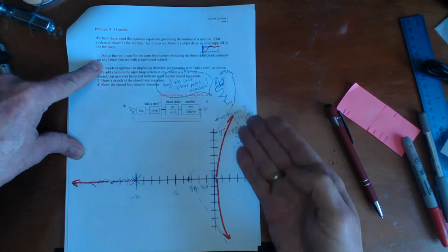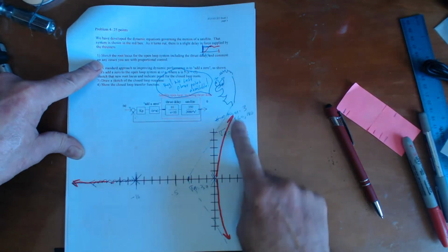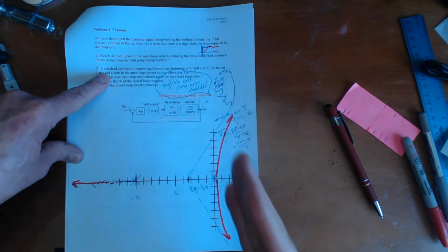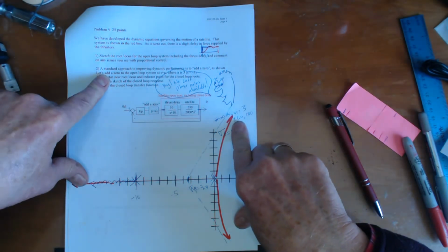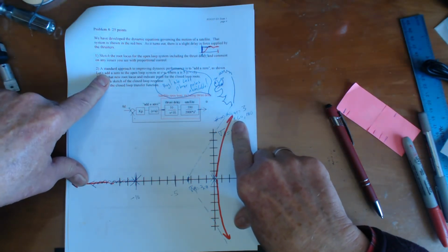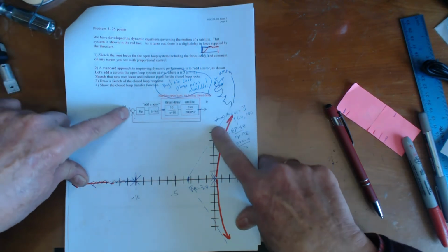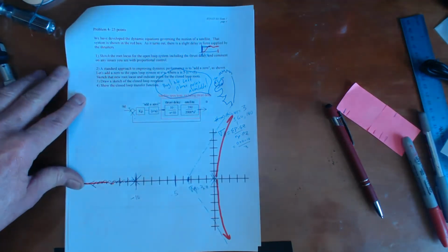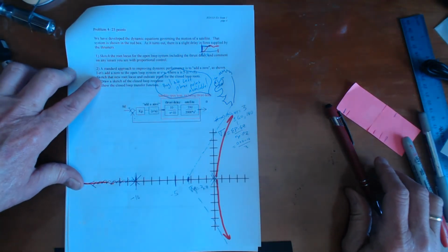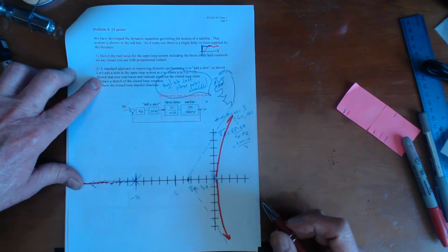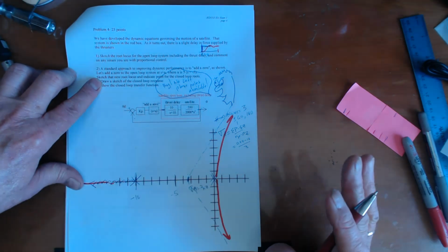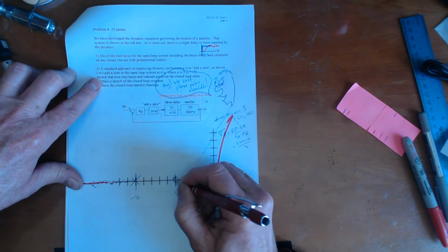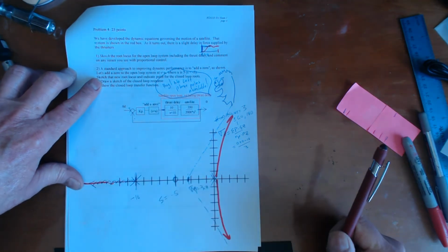If you just use proportional gain alone, you're going to run into problems. So a standard approach, if you don't like the dynamics that your root locus has, we haven't talked a lot about this, but I'm telling you, and I give you the answer: if you don't like the dynamics, just add a 0. Why not? Just throw a 0 in there. Here's a 0 that somebody's put in there for me. It's not clear exactly where all that comes from, but I'm going to put it at -5. So here is s equals -5, a 0.